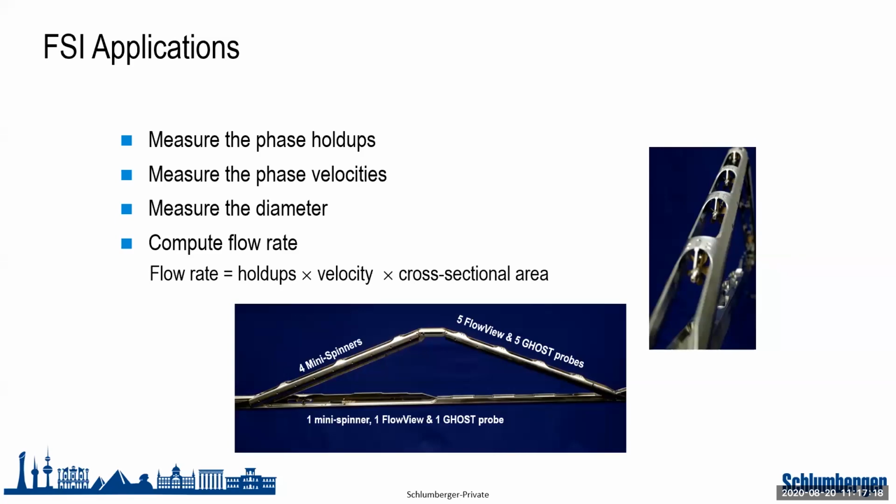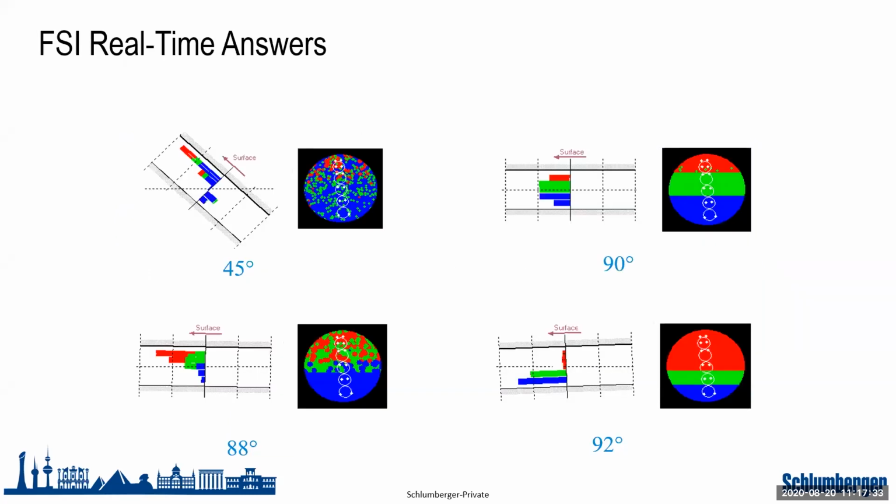It's going to contain a water holdup measurement and a gas holdup measurement. So we'll be able to localize our measurements in the different segregations that we have in the wellbore. So this is real-time information we get when we log this tool at different deviations.